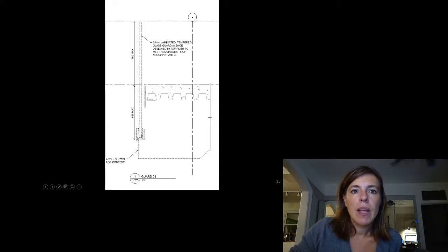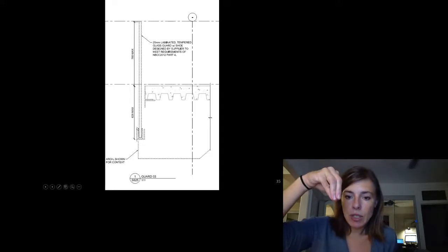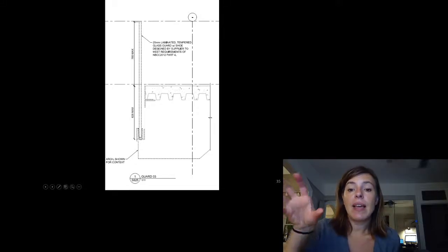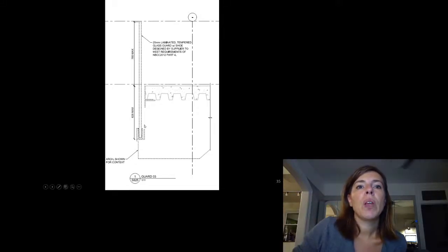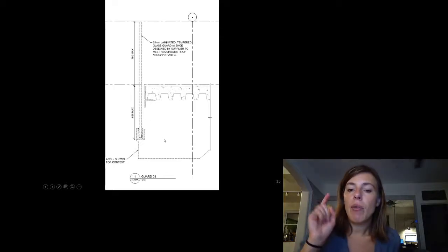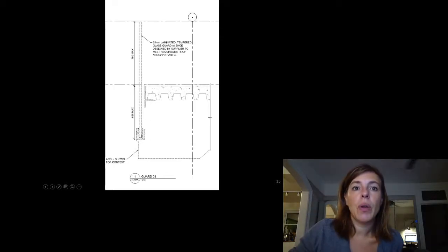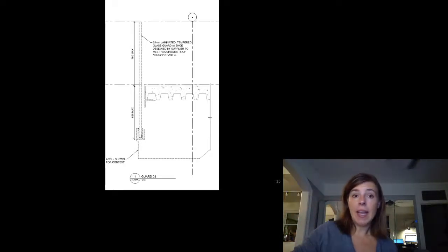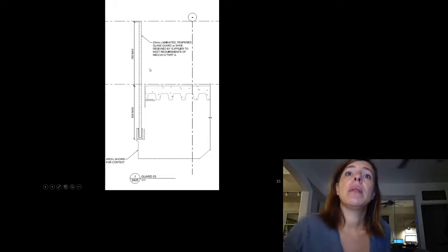Damn it. This shoe, remember, it has a screw that goes down into it. It needs to connect to something that can still resist that moment. So this one here was a placeholder for more detail, and I have a model of that I will show you. So this connected down to an angle that spanned between basically outriggers that connected back. We created a frame system here to resolve that couple.